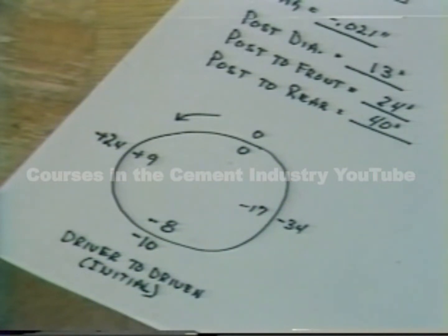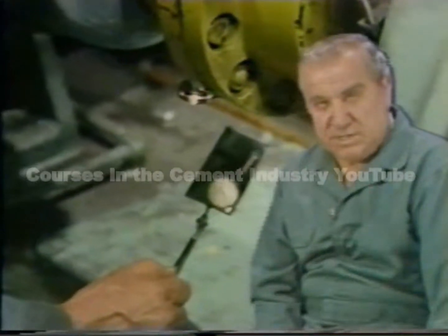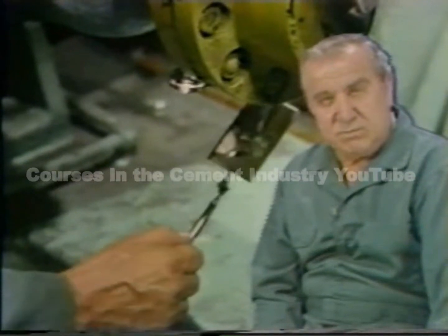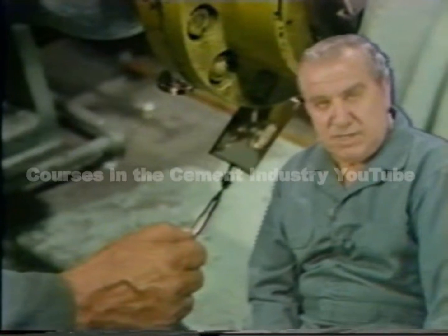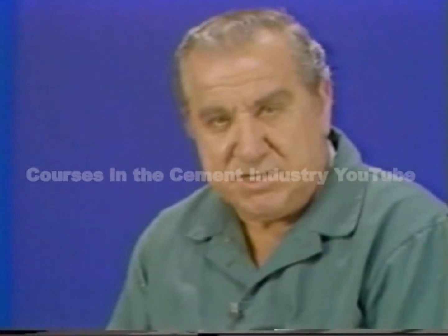We now have the information we need to start calculating movements to correct misalignment. But before we do that, stop and review this segment. Up to this point, we've gathered an initial set of readings, and we've determined that they're valid. The next step is to put the readings in a usable form and also to correct for rod sag. Let's look at the data sheet while I explain how these things are done.